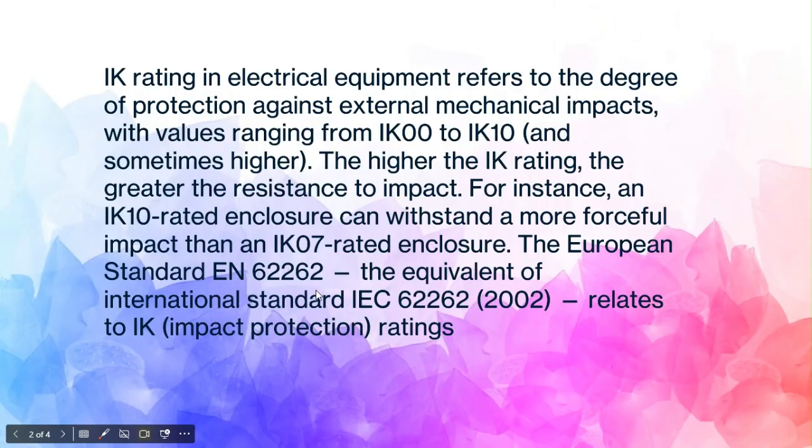IK rating in electrical equipment refers to the degree of protection against external mechanical impacts, with values ranging from IK00 to IK10 and sometimes higher. The higher the IK rating, the greater the resistance to impact. For instance, an IK10 rated enclosure can withstand a more forceful impact than an IK07 rated enclosure.